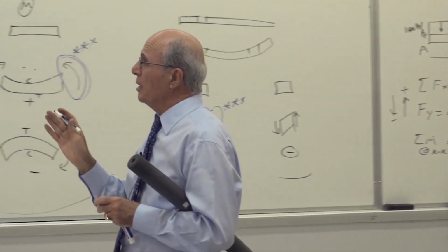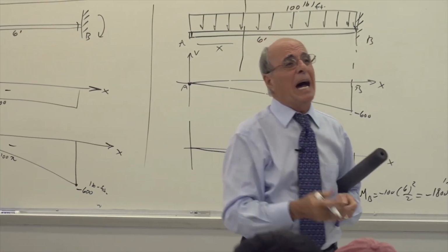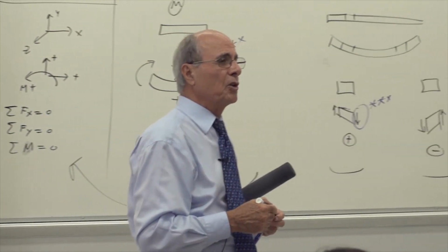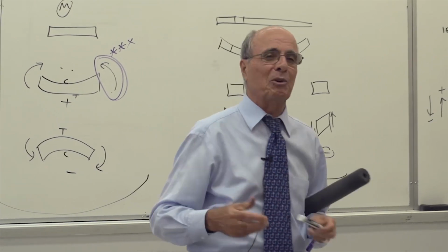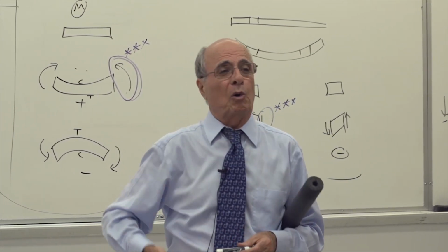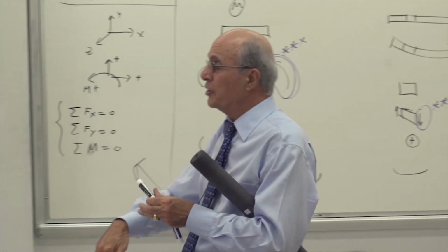Before point B, the shear is 600. After point B, is the shear going to change or not? Just answer me that. It's going to change. That's the whole point. How much is it going to change? By 900. But should I go up or should I go down? Now, because the 900 force is down.